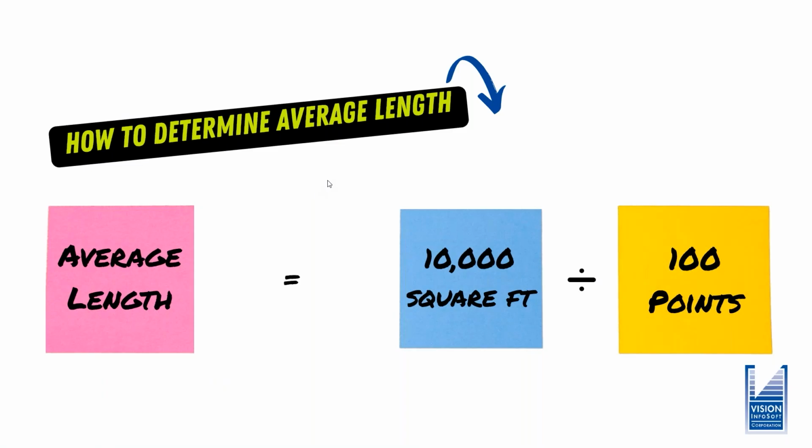The question was, are points the beginning and end of a branch circuit run, or just one end? The point is the outlet. Again, the outlet could be a switch, a receptacle, or a fixture. We're counting electrical items that need to be wired, and then we're trying to come up with the average distance between those.